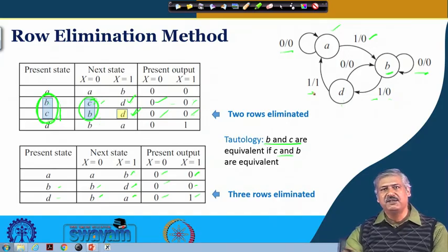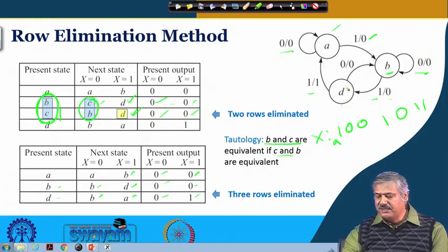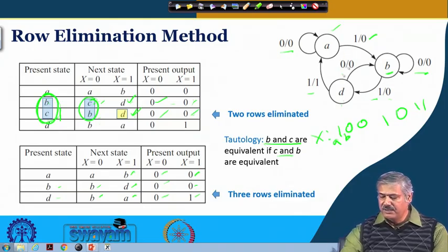So, this is the reduced state transition diagram, and you can give any random input sequence of x, say 1, 0, 0, 0, 0, 1, and so on, and examine it. If the current state is A, what will be the next state? The next state will be B, and the corresponding output will be 0. Then for 0, the next state will be B, output will be 0.